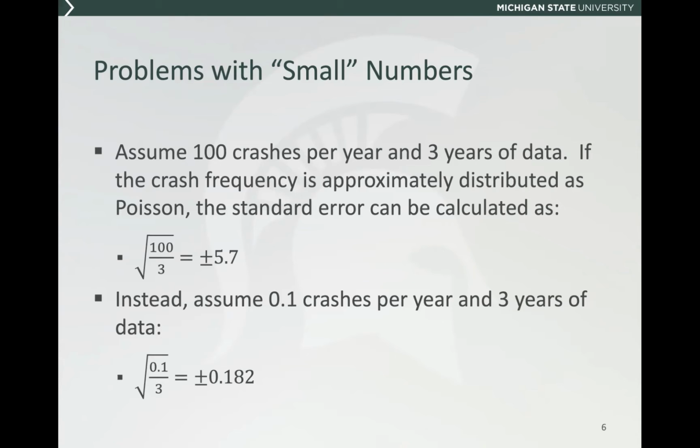And so what we try to do is use these more sophisticated methods, particularly when we have either very limited sample sizes in terms of the number of sites or the number of years of data that are available to us, or if simply the mean number of crashes we'd see year to year on a site-specific basis is small. Because in those circumstances, if we see a regression to the mean effect, it's going to be very large just relative to the underlying uncertainty. As we get larger number of crashes, so particularly at high volume sites as an example, that inherent variability tends to be less, and regression to the mean as a consequence tends to be less severe in those instances. And so this is a particularly big problem with small samples in various definitions, okay?